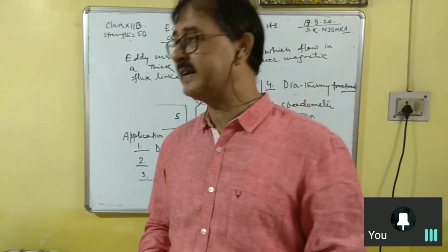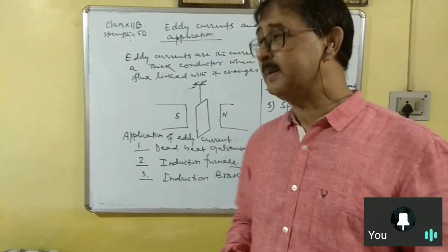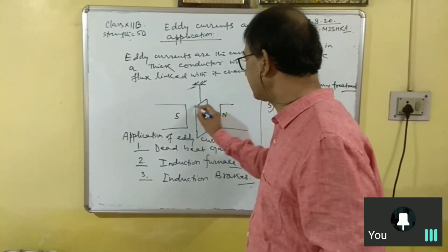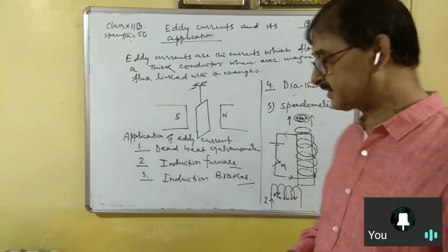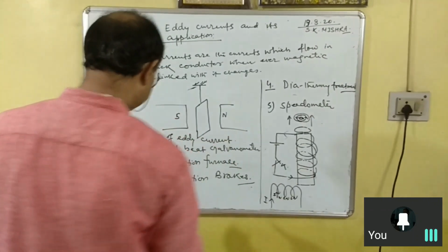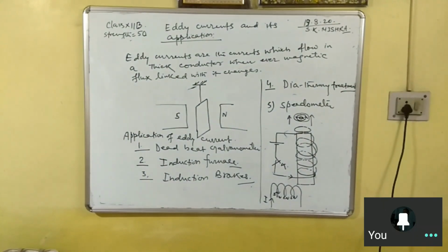Some way is there through which you can minimize it. To minimize the eddy current, the rectangular sheet is cut in such a way that this area can be reduced. So I am showing you the next diagram. Take the snapshot. Okay. Taken.